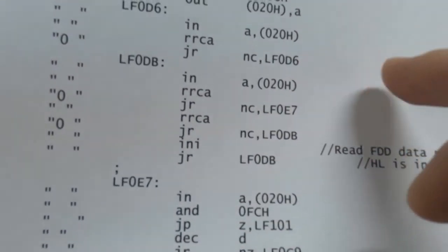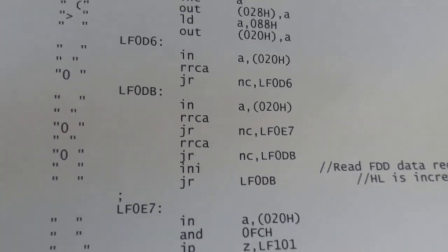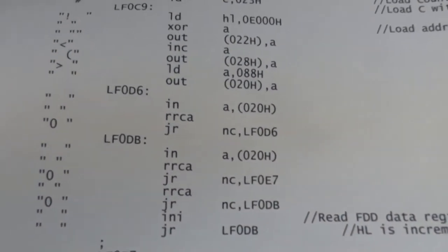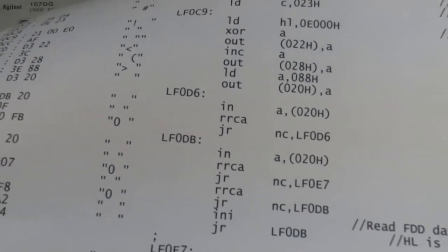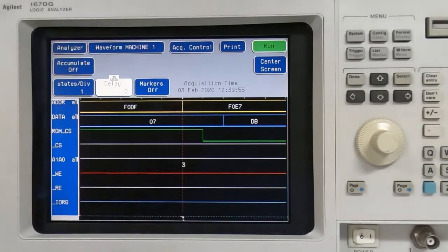We're going right through the initialization, we're going through the reading and writing of registers. Everything's working except that it's never actually reading any data. Everything else works, it's just there's never any data in the data register within the device. So I'll continue searching through this, but it does look like this is as far as we can go in the actual code because this is doing what it should be. So it looks like there is a fault, most likely in the data slicer chip. Unfortunately, I don't have a spare one to try, but it looks like that's where the fault lies. I'll try and get hold of a replacement to test.